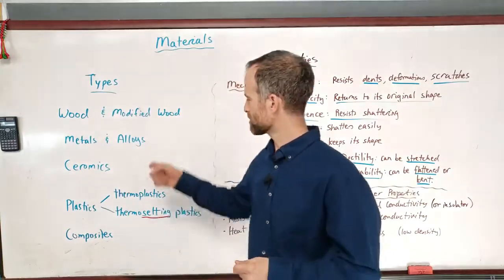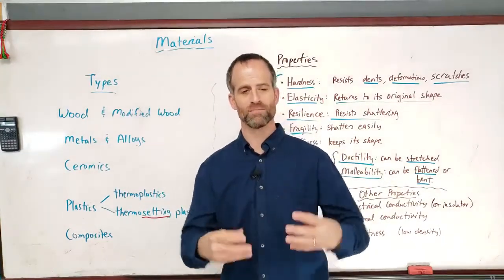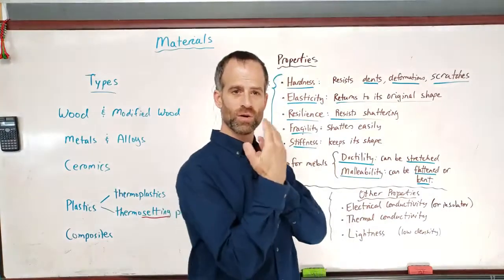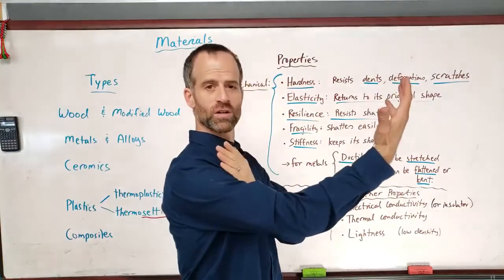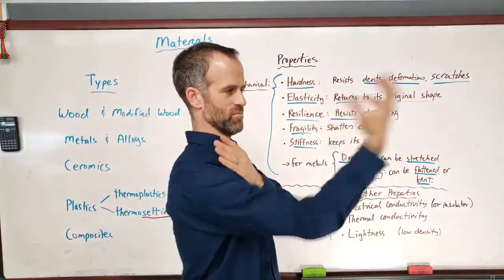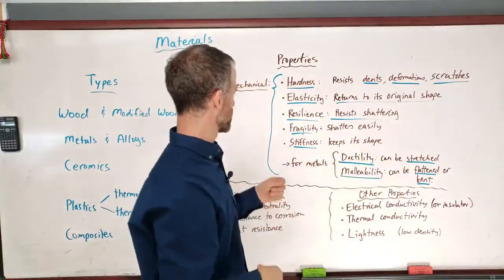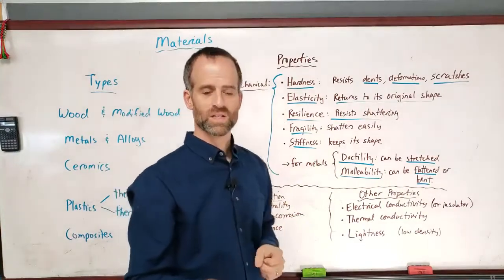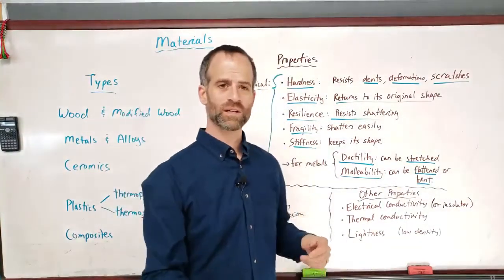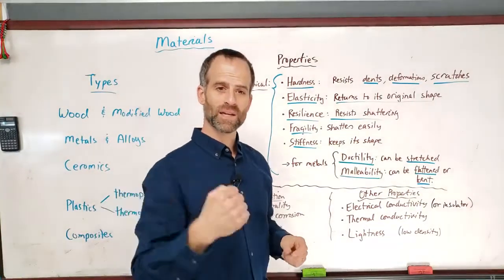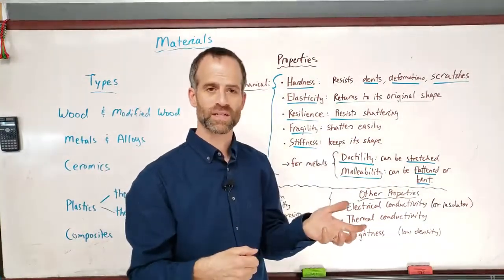That's one way to modify the property of a metal. You've made that metal much more rigid. Now the problem is, as you make the metal stronger, it becomes less resilient. So if you quench harden a sword, it becomes very hard, it doesn't bend, but if you hit something, it can shatter easily.